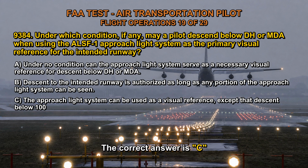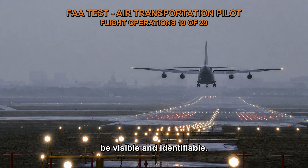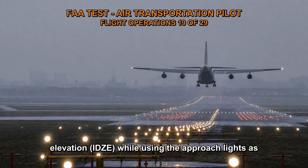The correct answer is C. Feet above TDZE requires that the red light bars be visible and identifiable. A pilot may use the approach light system as their only visual aid as they descend below the MDA or DH. However, unless the red side row bars are also clearly discernible and recognizable, the pilot may not descend below 100 feet above touchdown zone elevation, TDZE, while using the approach lights as a guide.